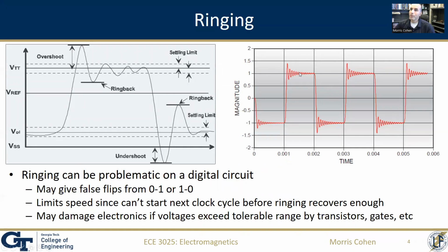And unfortunately, the very tactics that we use to most efficiently deliver the voltage from a source to a load, from a transistor to the input of the next NAND gate, the worse we actually make this ringing problem, right? Because we're going to have a high positive reflection coefficient on the load side, and a very high negative reflection coefficient on the generator side. And that's how we get ringing.